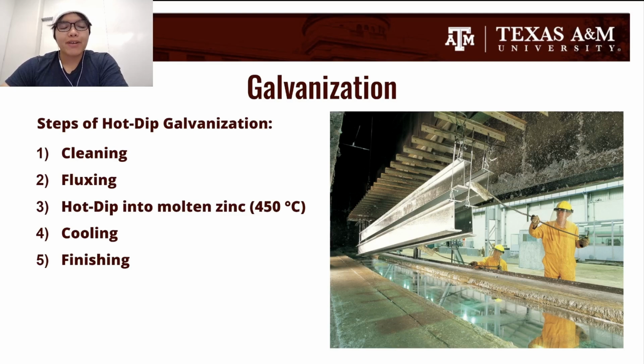One of the benefits of galvanization is that it is very low maintenance in the way that it does not need to be regularly maintained over the time period. It is also cheaper considering that zinc is very common in the earth. One of the cons of galvanization is that it only lasts up to 50 to 100 years due to the zinc beginning to corrode away and then corrosion eating away at the metal inside.